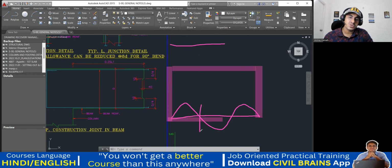This particular point you should stop, because it's a point of contraflexion. Or if you had started from this side, you could have even stopped at this particular point. I'll make it in a different color. This was a point where I should have stopped my concreting, or I could have stopped here. Why? Because these are the points of contraflexion, where your bending moment is minimum. So if I stop my concreting here, nothing will happen. But if I stop somewhere in the middle, where your sagging bending moment is maximum, the moments are higher, and you have stopped your concrete.